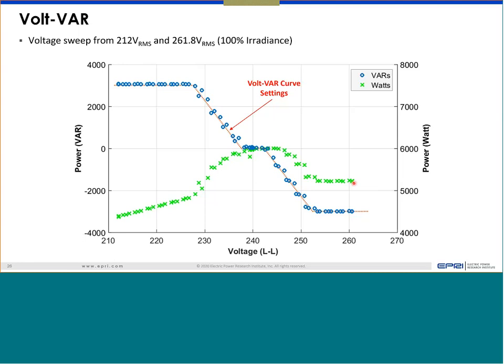I'm going to guess you're current limited. Exactly, absolutely right. So what happened on the high voltage side, voltage goes high. To maintain the power, it needs less current, which is perfectly okay because it's below its threshold. In the low voltage side, it can try to increase the current, but at a certain point, it will hit its current limit.